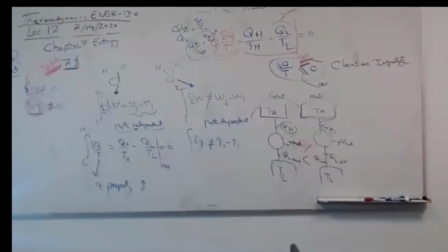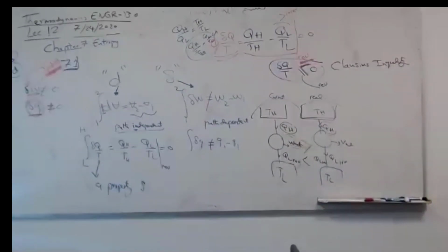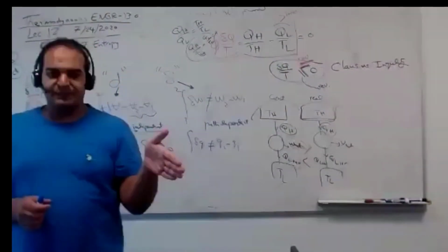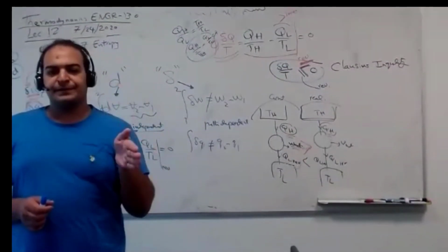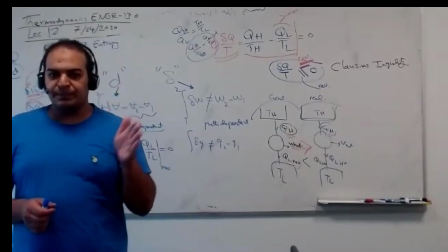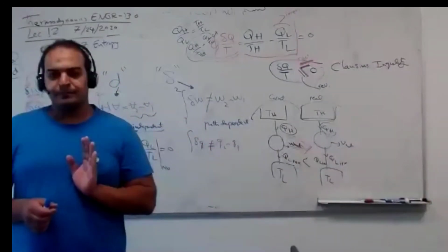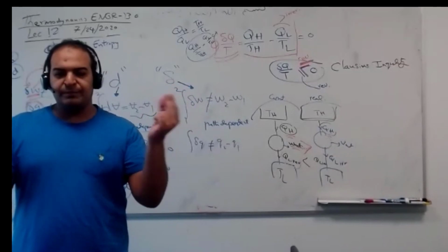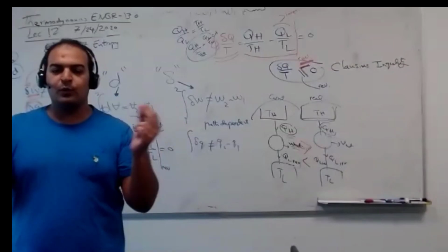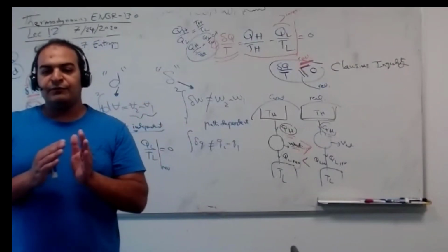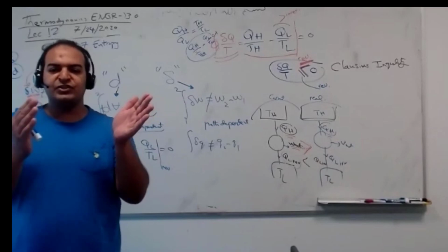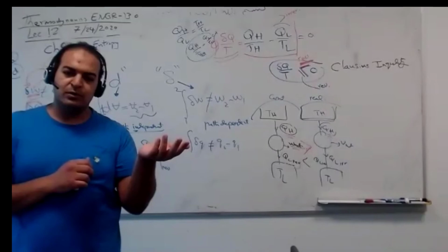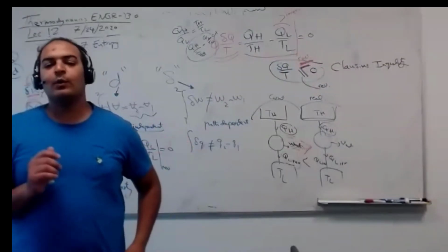Okay, guys. If you look at the steam table A4, temperature is the input. The first left column is T in Celsius. The next one is pressure, P, saturated pressure and temperature. From F to G, from liquid to vapor, from X equals 0 to X equals 1, you find the next two columns are VF and VG. VF is for X equals 0 and VG is for X equals 1.